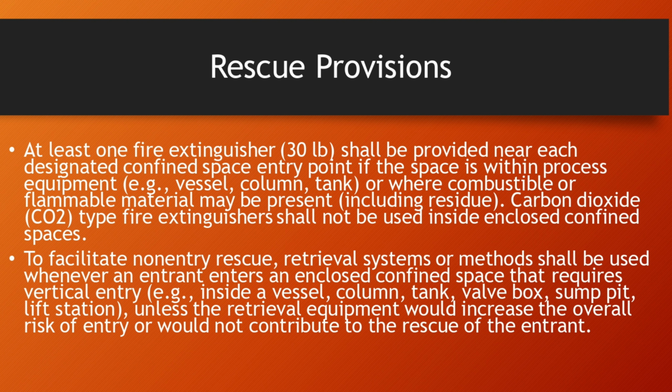To facilitate non-entry rescue, retrieval systems or methods shall be used whenever an entrant enters an enclosed confined space that requires vertical entry, for example, inside a vessel, column, tank, valve box, sump pit, lift station, unless the retrieval equipment would increase the overall risk of entry or would not contribute to the rescue of the entrant.